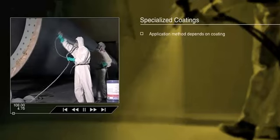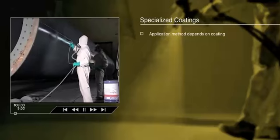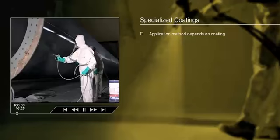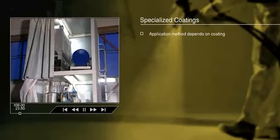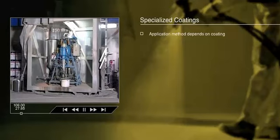Application method depends very much on the type of coating that is being used. Some specialized coatings in particular may be restricted to a specific application method. Some coatings, which are 100% solids, for example, can only be applied using special equipment such as heated, plural component airless spray pump or by hand.